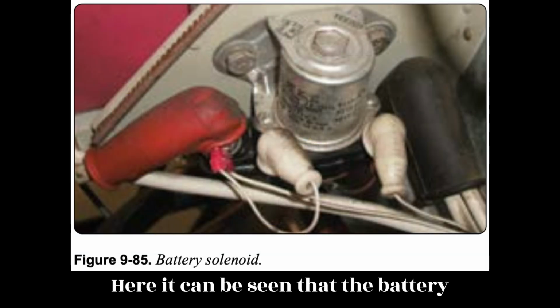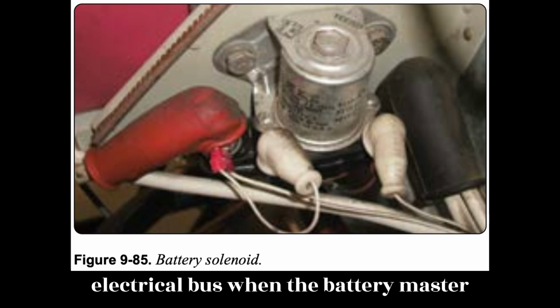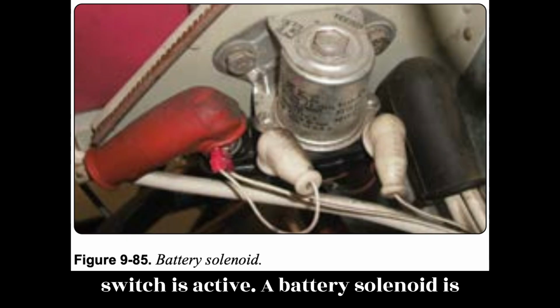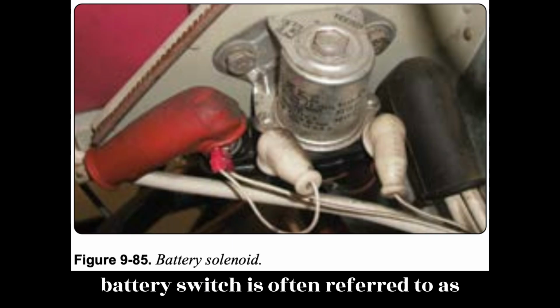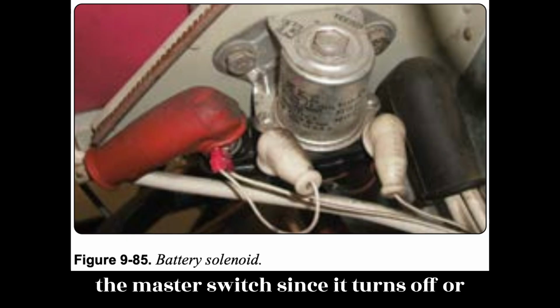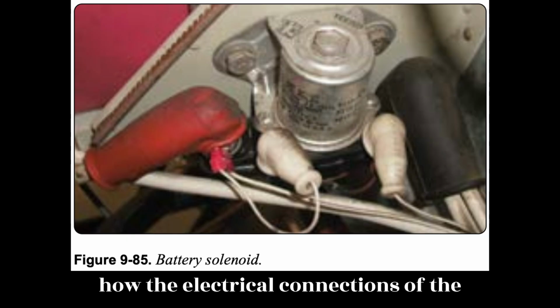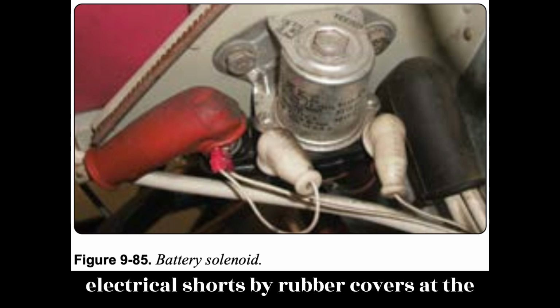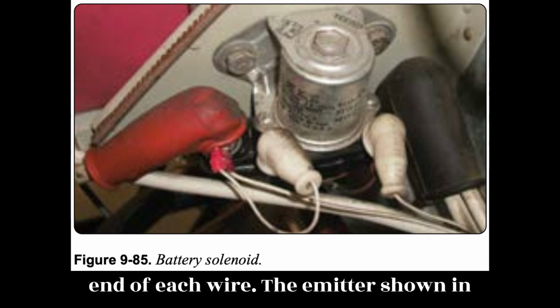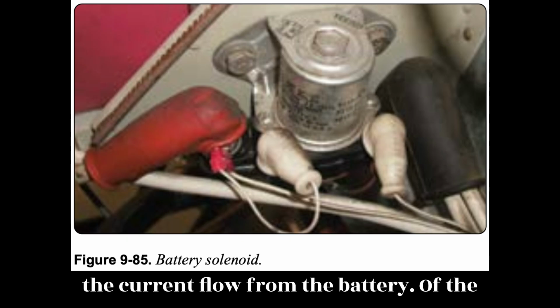Here it can be seen that the battery positive wire is connected to the electrical bus when the battery master switch is active. A battery solenoid is shown in Figure 9.85. The battery switch is often referred to as the master switch since it turns off or on virtually all electrical power by controlling the battery connection. Note how the electrical connections of the battery solenoid are protected from electrical shorts by rubber covers at the end of each wire. The ammeter shown in the battery circuit is used to monitor the current flow from the battery